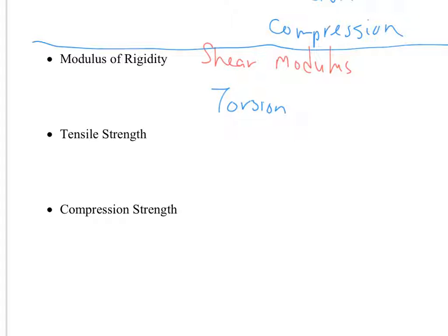In a minute, we're going to talk about the difference between me compressing here. If I just compress, I can't really break this. But if I fix this end and push down hard enough, it'll eventually snap. This is called buckling. So we're going to see that in compression and in tension, the properties are different. So you have to know what state the actual member of your structure is in. If it's in a state of compression, you might want to use one material as opposed to another.